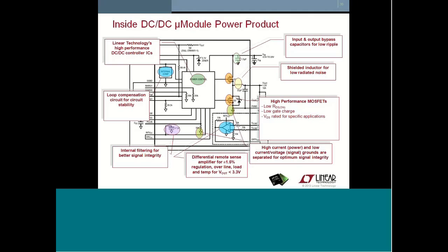We use shielded inductors, and great care is given to the layout of the substrate to minimize radiated and conducted noise. Also, special attention has been paid to the layouts and grounding to maximize regulator stability under a wide variety of conditions.